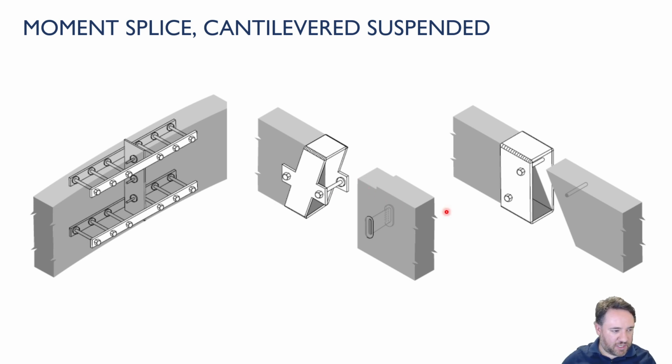We don't want to use big plates here because imagine I put a big plate that was this entire size and I connected those together with bolts, then I would have a shrinkage problem. If I have bolts top and bottom and those bolts are held in place by a steel plate, that steel plate will not expand and contract due to moisture, but the wood that's behind will want to contract.